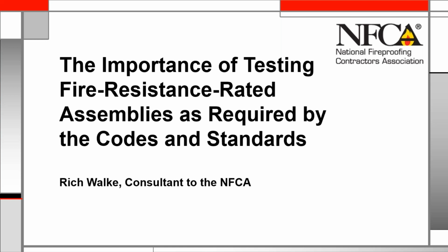Similarly, the standards also require beams, floor ceilings, and roof ceilings to be loaded during the fire test. Generally, assemblies are loaded to their maximum design capacity during the testing, although there is an allowance in the standard to test something other than a maximum design capacity, as long as the resulting report and listings clearly state the allowable load that was tested. Once again, for a number of reasons which we'll discuss shortly, testing assemblies at something other than the maximum allowable load is a less critical evaluation.